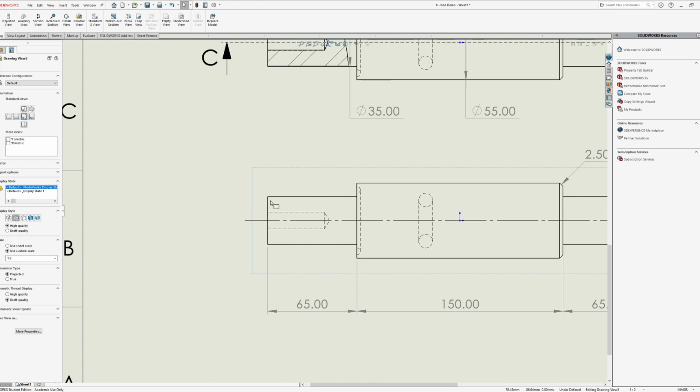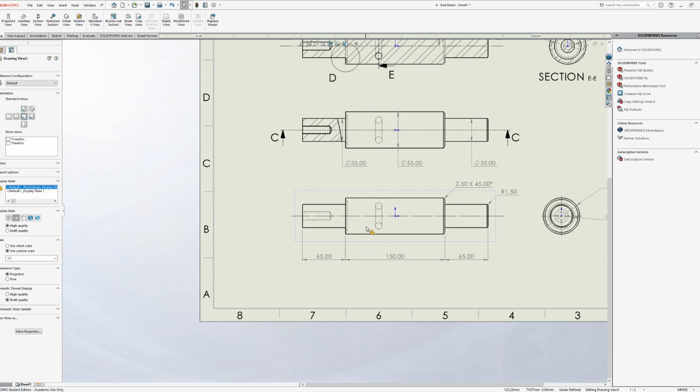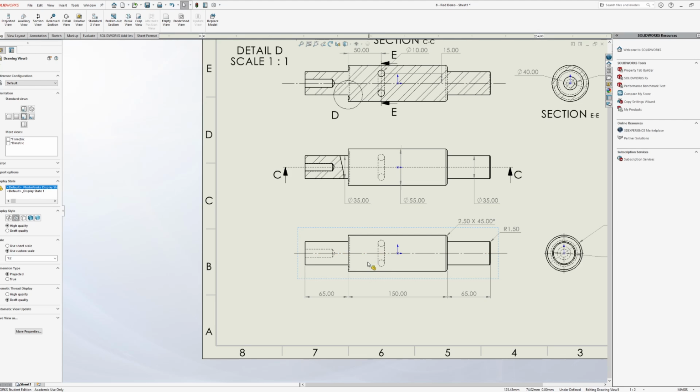So technically that hidden line visible is just a good way of being able to see other geometry that you might be missing if you're not looking at it immediately. So that first picture, the one in the middle, there's actually no cross section going on there. It's just a front view where you're saying, okay, there's other stuff happening here. I can't actually see what's going on here. I don't necessarily need a cross section, but I know there's further detail to this figure than what meets the eye.